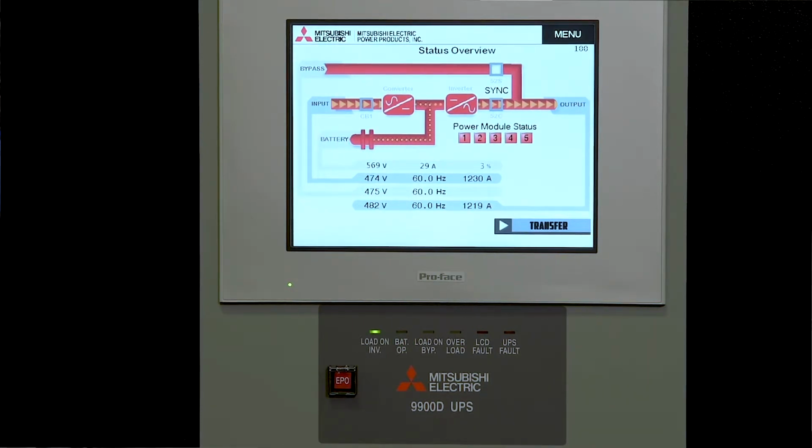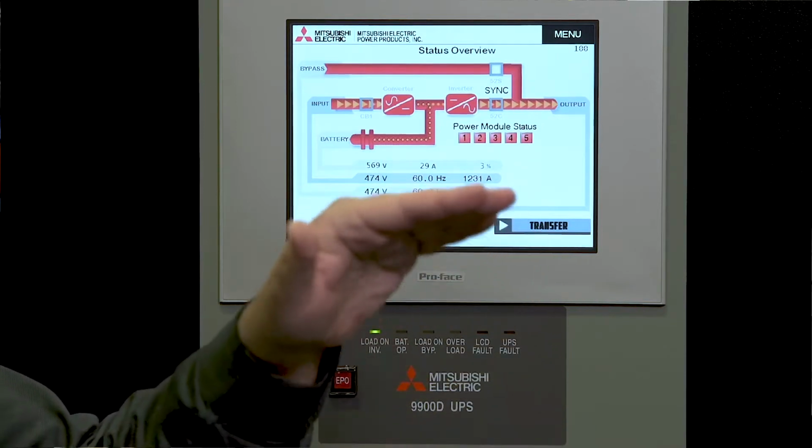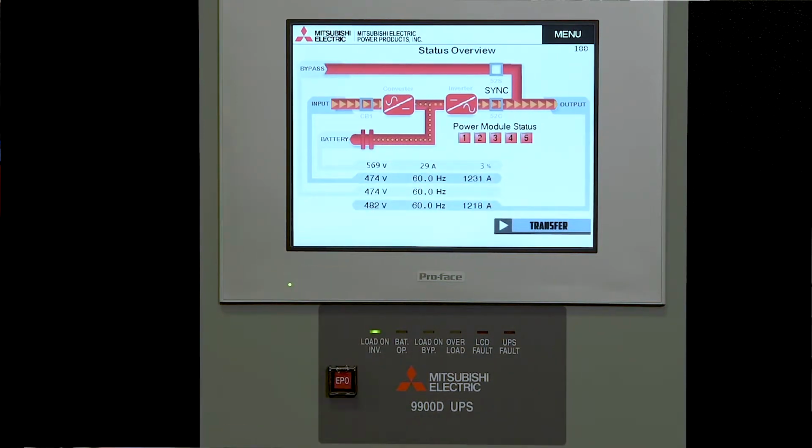It'll run for a period of time. We'll close the AC input breaker back in, and then the UPS will reassume the converter operation, walk in the load to the converter, and slowly walk off the battery, and then provide pure UPS power out to the load the entire time. So now we're going to begin that test.